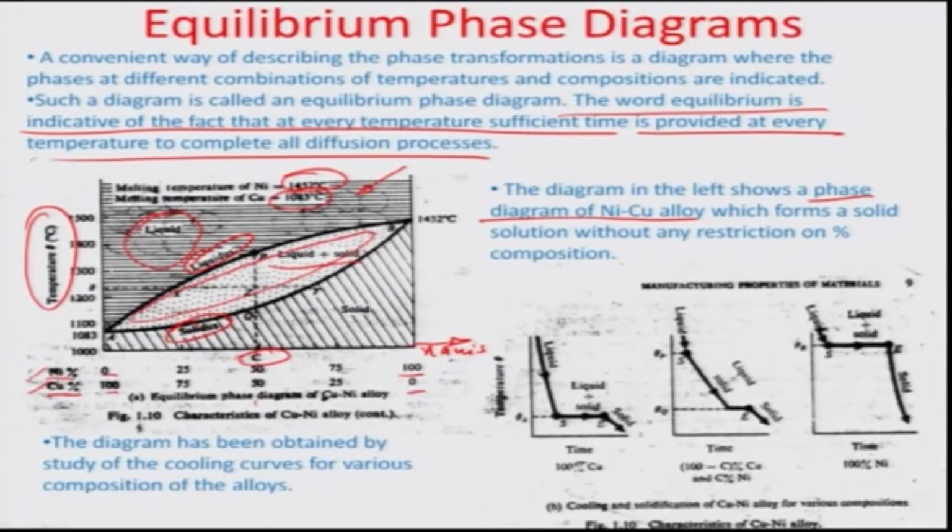That means the liquid is partially solidified. There are some solid chunks here and there is some liquid until the temperature comes to this particular point from P to Q, where it has completely solidified. So, complete liquid, complete solid, and in between this dotted region showing liquid plus solid. That is how the phase diagram is mostly plotted.